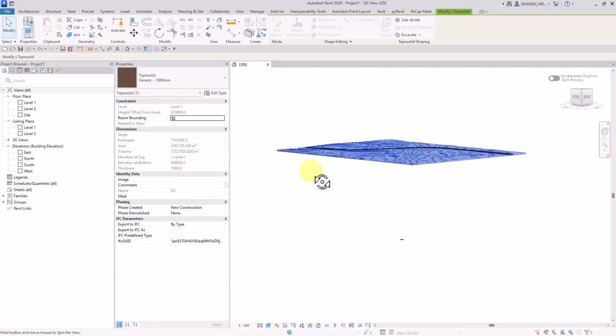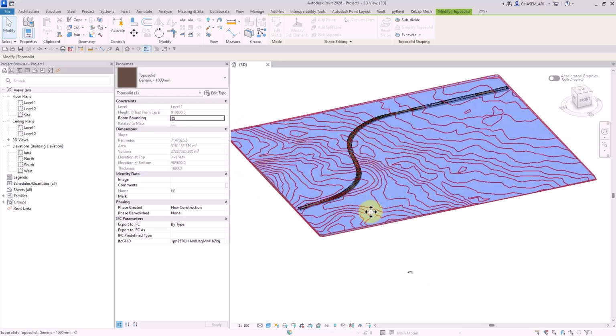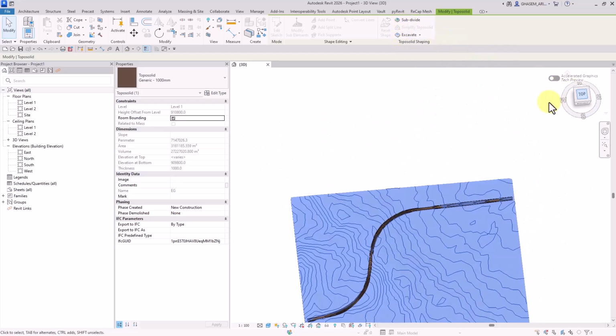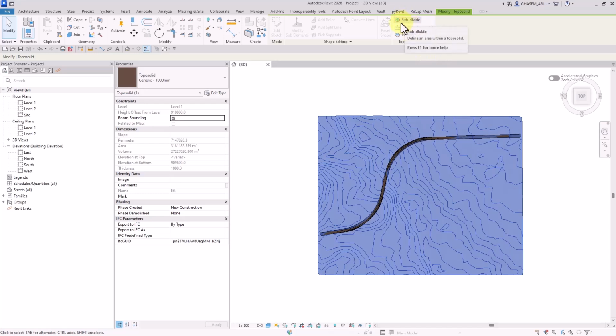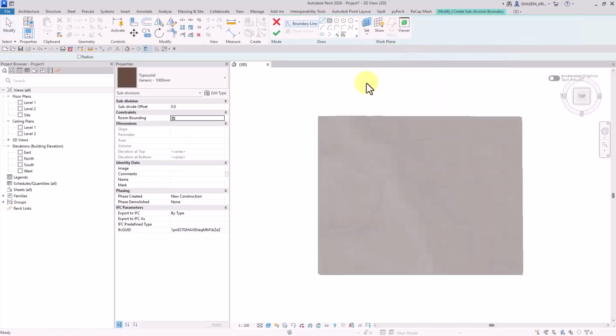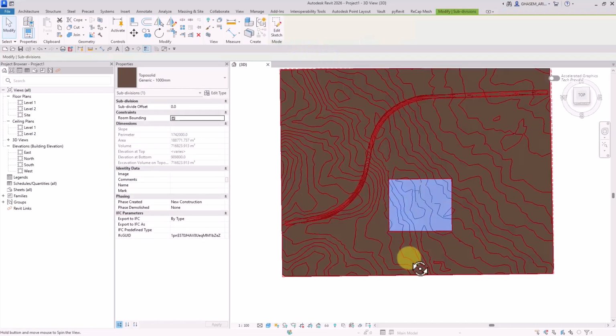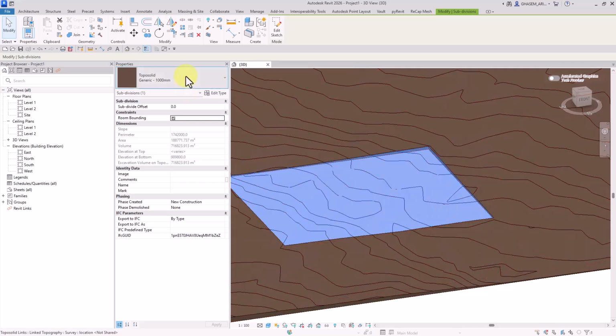Now guys, after all of this, we can select this and up here use, for example, excavation or even subdivision. Well, honestly, this is quite interesting, guys. We just linked a civil 3D file that was saved in cloud inside Revit in our viewport, and now we are able to use these items on it like subdivide. And as for another perk, guys, now we actually have access to more information when we want to create topographies in Revit.